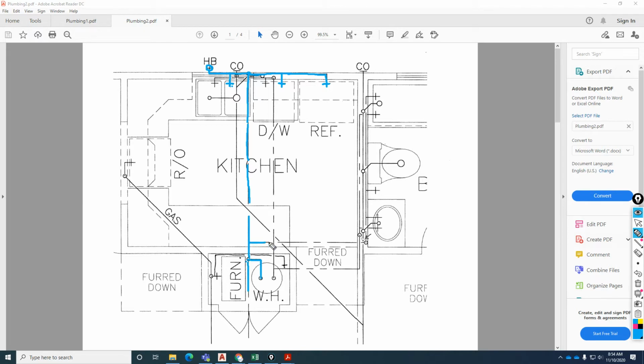Okay. So cold water goes this way underground, comes up out of the ground, comes this way, and we're going to provide a cold water valve for the lavatory. We're going to continue and provide a cold water valve for the water closet. Whenever you flush, the tank needs to get filled with water once again, cold water specifically. And then cold water for the tub, combination tub shower.